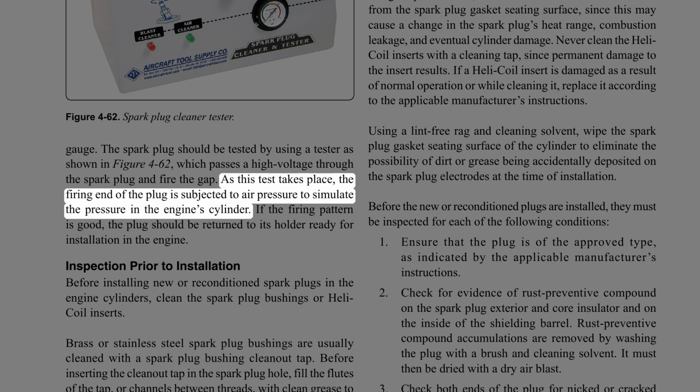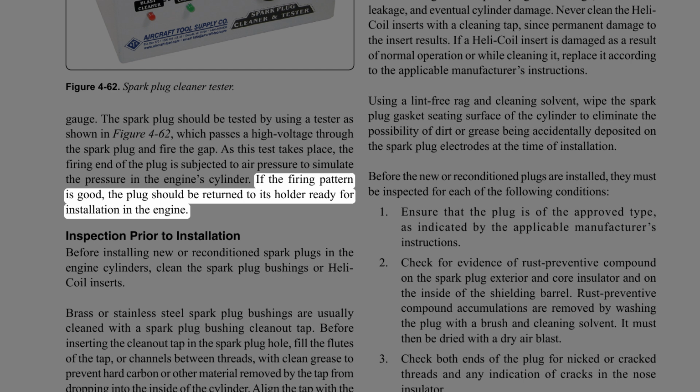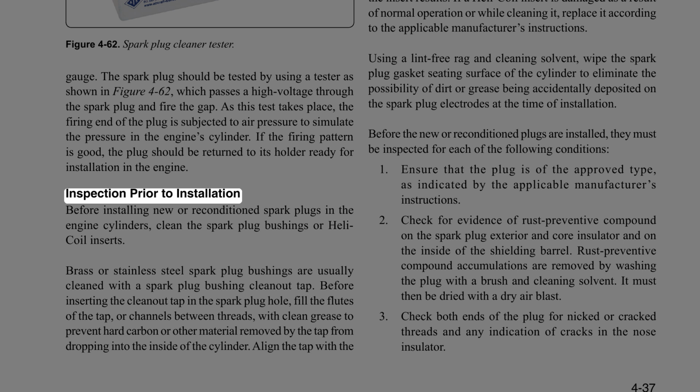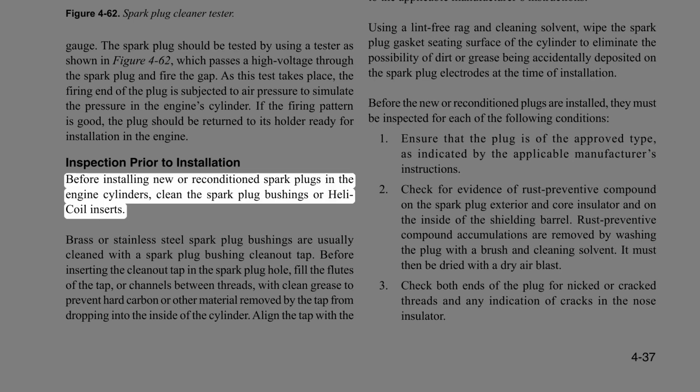As this test takes place, the firing end of the plug is subjected to air pressure to simulate the pressure in the engine cylinder. If the firing pattern is good, the plug should be returned to its holder ready for installation in the engine. Inspection prior to installation. Before installing new or reconditioned spark plugs in the engine cylinders, clean the spark plug bushings or helicoil inserts.